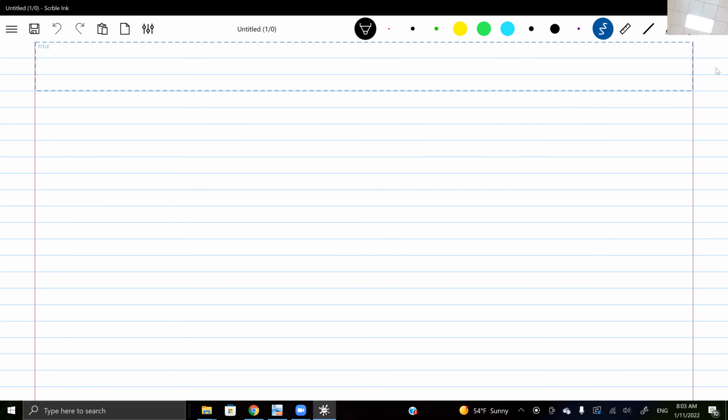So what is the conclusion of the last couple of lectures? The conclusion is that for the whole airplane, the lift coefficient is linear in the angle of attack, a constant plus some constant times the angle of attack. So this is the lift coefficient for the entire airplane.